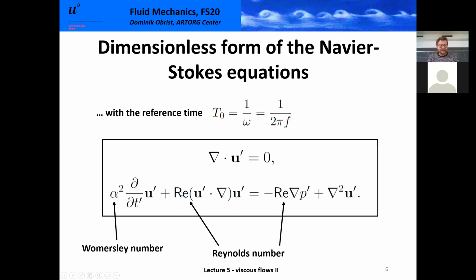In situations like in a microcirculation or like in the alveoli, the Reynolds number is very small. Likewise, if we were to compute it, the Womersley number is very small. This will allow us to forget, and I'm really saying forget, about these terms on the left, the first term and the second, unsteady term. So both can be considered close to zero. This is not the same as what we have done in the previous lecture. In the previous lecture, we got the exact solutions. There, the terms drop out exactly because of boundary conditions, because of symmetries, and so on. What we do today is a simplification.